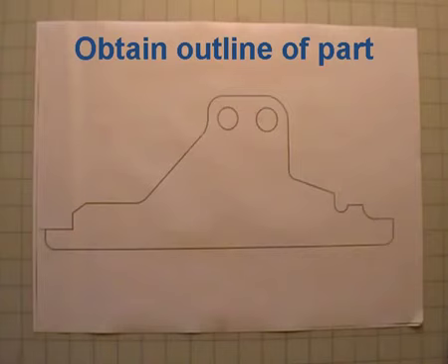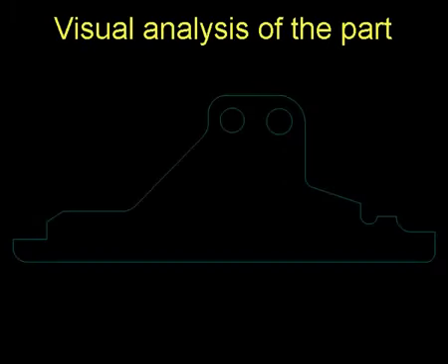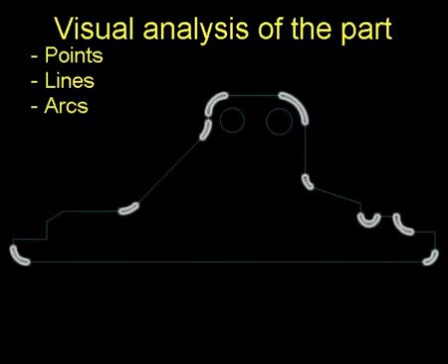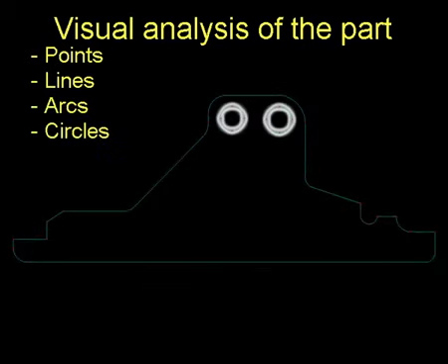The first thing to realize is that we are programming an NC machine. You have all the logic of cutting, insides before outsides, entries and exits, and cut to the left or right. First, you need an accurate pen drawing. Never put heavy weights on the digitizer surface. If you analyze an engineering shape, it's made up of the basic geometric elements of points, lines, and arcs. Full circles are a special type of arc.